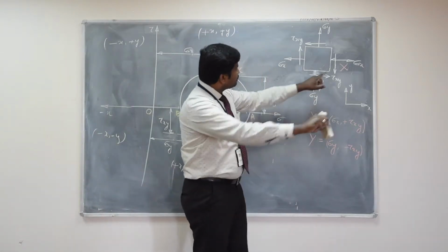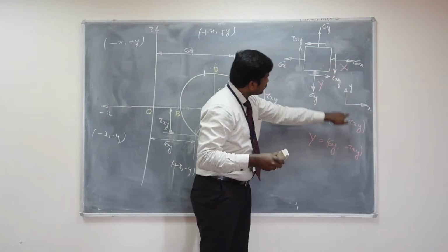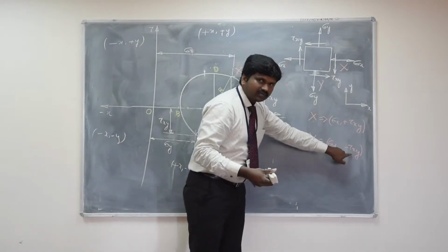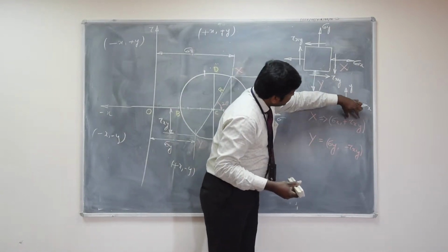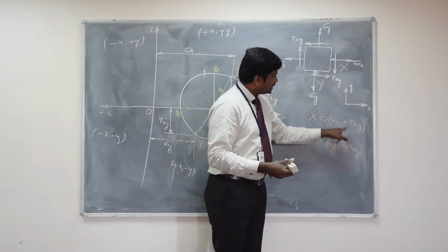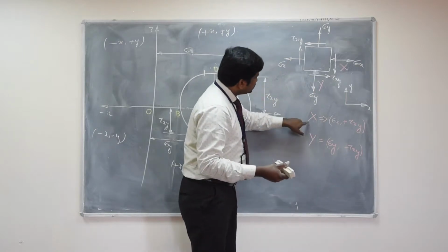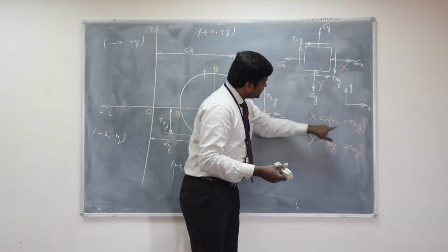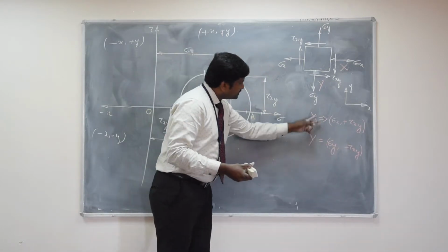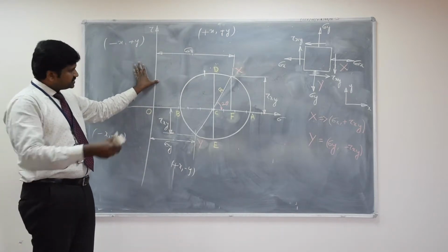With respect to that, this is the clockwise shear stress, clock above, positive. This is the counterclockwise shear stress, counter below, so negative. If you write the sign convention of one shear stress, the other one will obviously be the opposite. So if you write one, you need not check the other, straight away you write the opposite sign. So the x face coordinates and y face coordinates are written like this. Now these x face coordinates and y face coordinates have to be reproduced onto a Cartesian coordinate system with the proper sign convention.